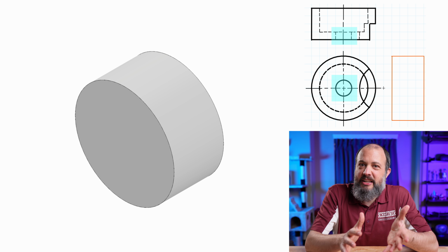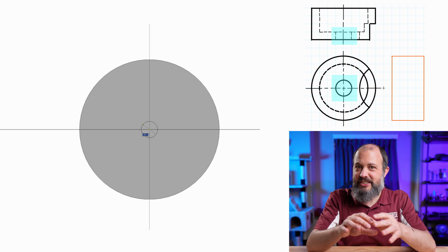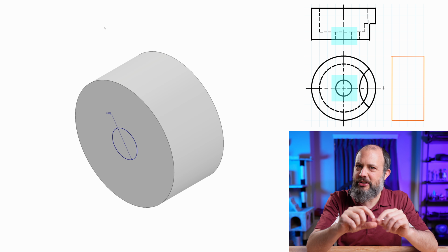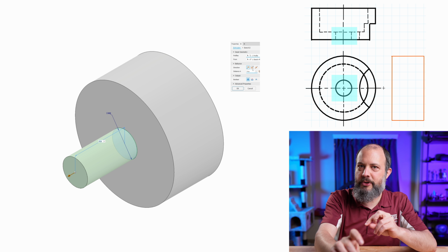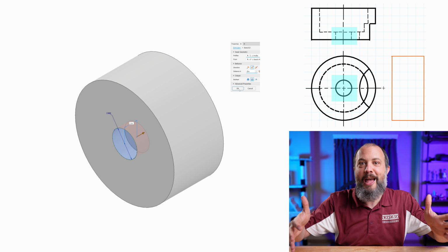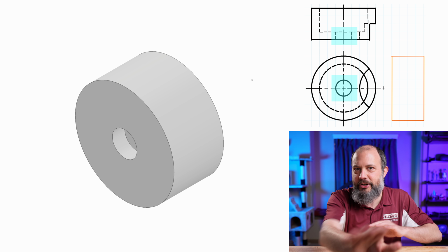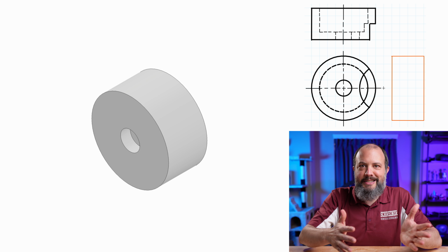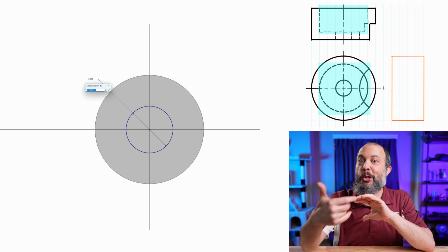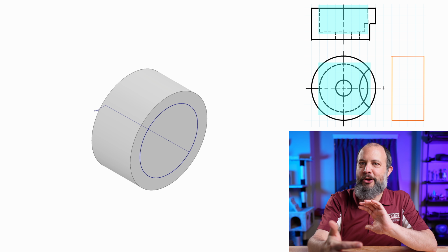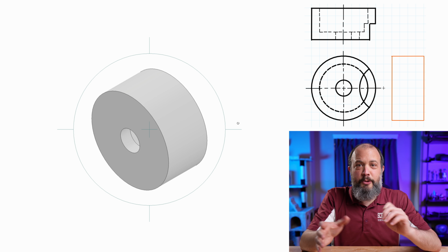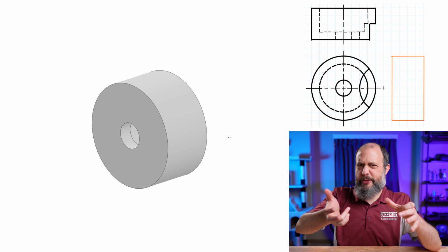Maybe the easiest thing looking at this shape is in the very center of the cylinder, there's a small hole. From the top view, this small narrow cylinder looks like it only goes part of the way through, but of course, that's because it reaches another wider diameter hole. So I'm going to go ahead and just extrude it all the way through the whole length. But then next, I'm going to rotate the cylinder around to the back side and draw that larger diameter hole that only goes part way through and sort of meets the smaller hole in the middle. And now we've essentially made like a bucket with a hole in the bottom.